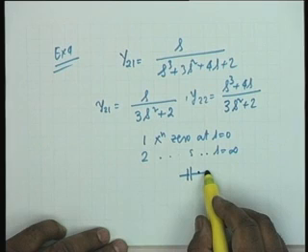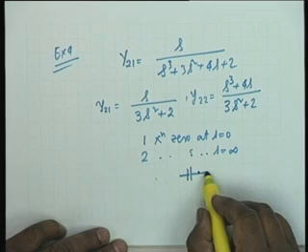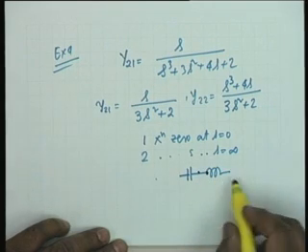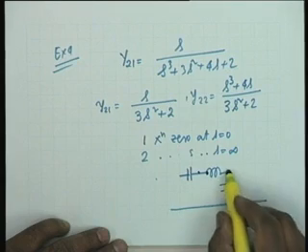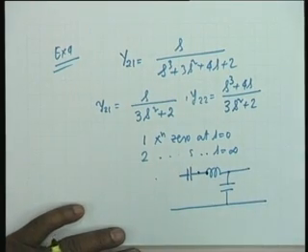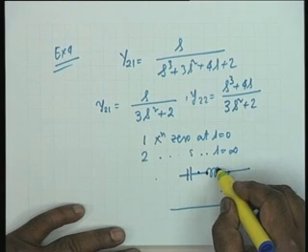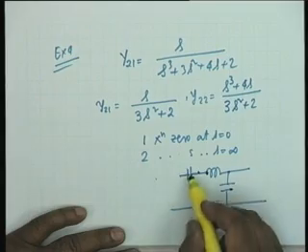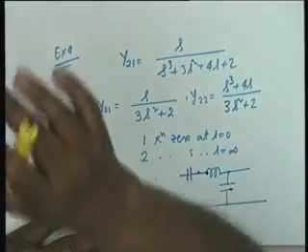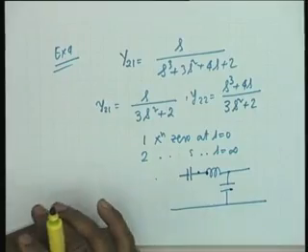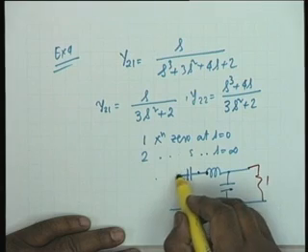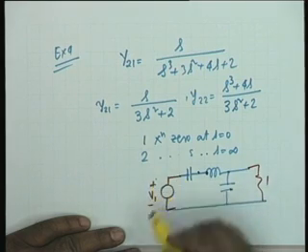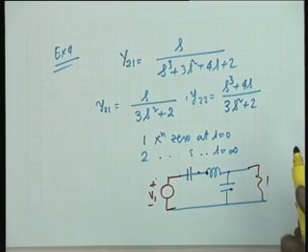Okay, where would you put the capacitance? First series inductance, then a capacitor. Will this do the job? This takes care of transmission zero at infinity because there is a 1 ohm resistance here. And this takes care of the transmission zero at the origin. This is a perfectly valid synthesis. Absolutely wonderful. All that we have to do now is to add this 1 ohm and add the voltage generator here. But how do you synthesize now?